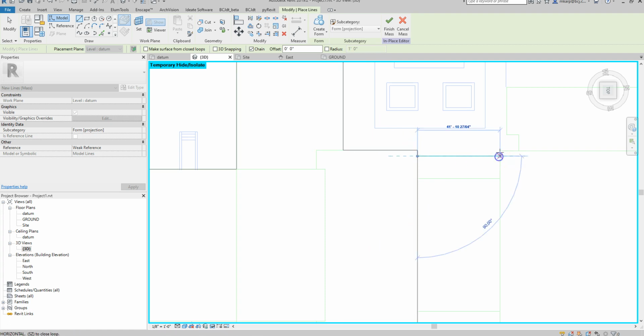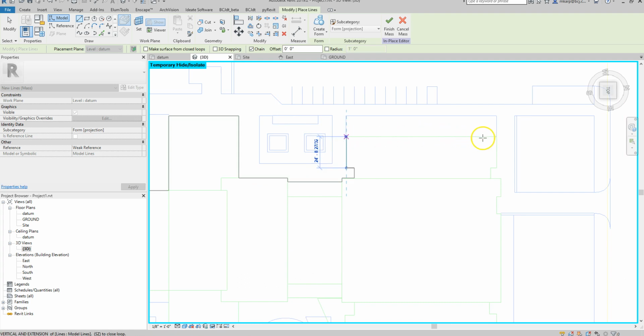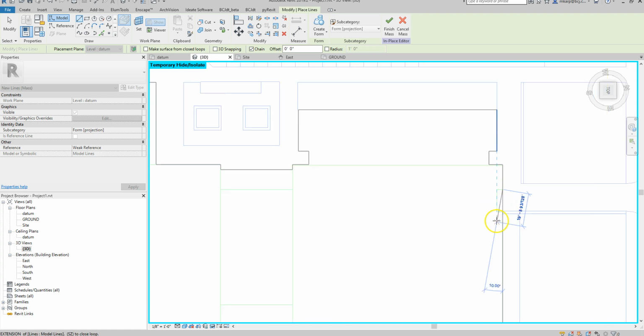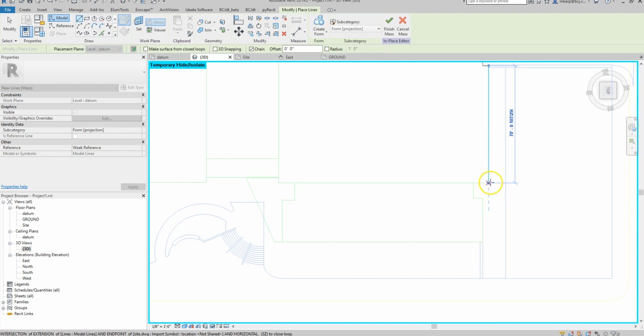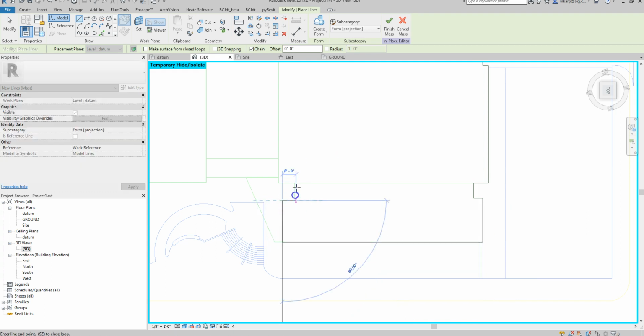What you can also do, if you want to, is take these 3D DWGs into Rhino and create them into surfaces and into a solid, and then we can actually use these shapes and bring them in as an SAT file into a Revit conceptual family, drop them in. That way we can preserve some of the detail without necessarily having to trace everything. I say that as I'm tracing everything.